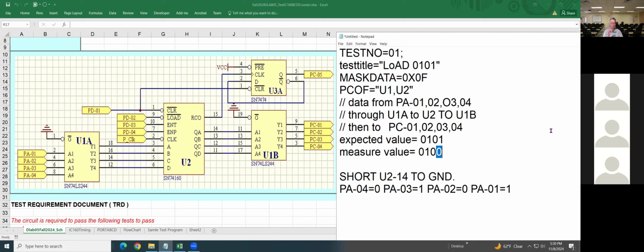But you've got to follow the line. Pin 3 on U2 comes out of U2 and goes to the output of QA, pin 14. So you need to see what you measure at U2 pin 3.